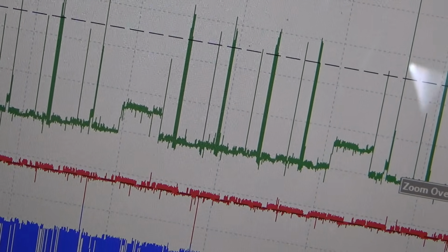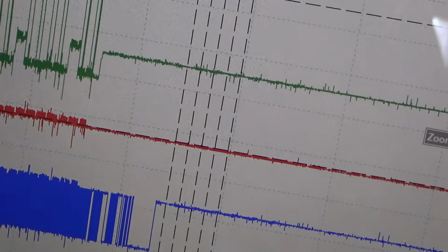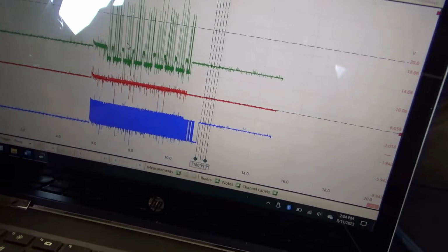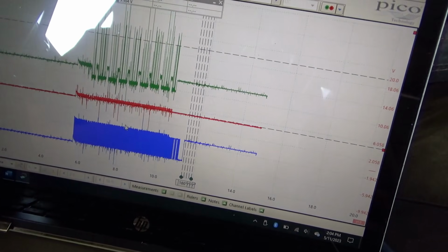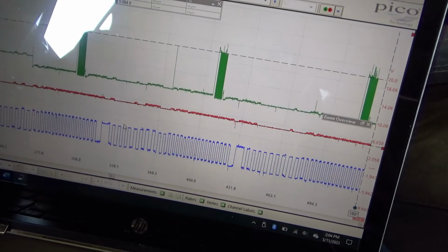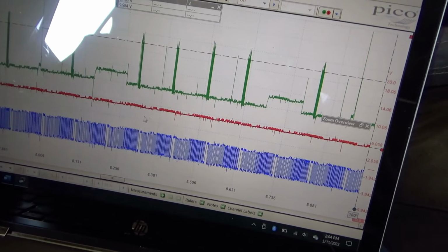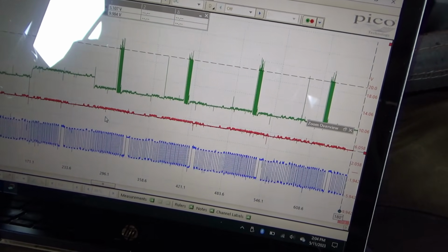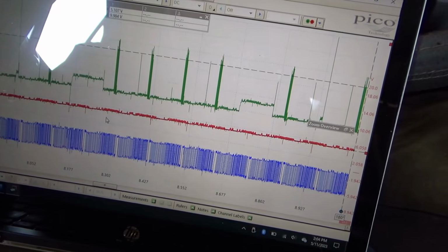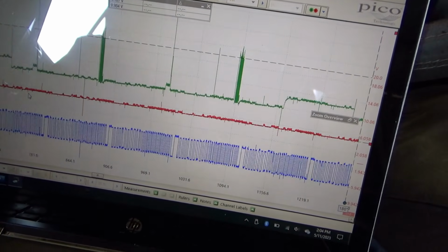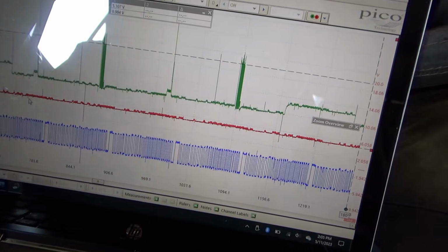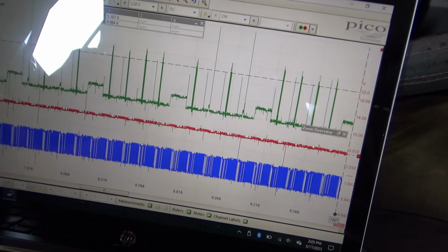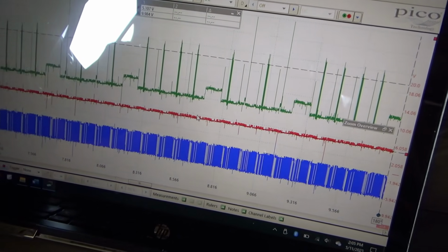So it doesn't like something about this camshaft position sensor signal, but what could it be? We know the sprocket's right, we know the timing is right. It just blows my mind. So there's no cam signal right now, and it's still firing the injectors on every crank revolution just from the CKP. Exactly the same way. So maybe it's trying to start, but it doesn't cough, it doesn't do anything.